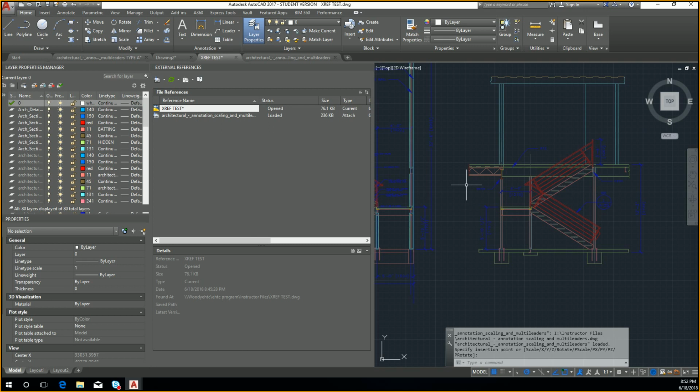So if you click right now, if you haven't exploded the blocks yet, on blocks, expand it. On the top there, see how the drawing is not in there? And then click on view items you cannot purge on the top there. Open blocks again and scroll down to the bottom. Right there, see how the solution drawing is there? Because it's still living as a block. You cannot purge the block until you explode it, because then you will have removed any living blocks.